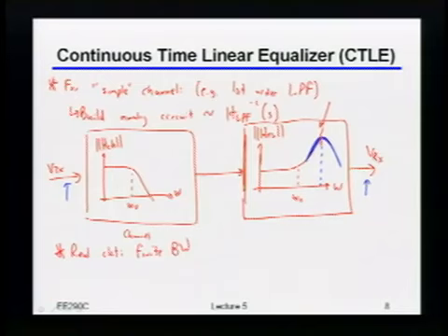Okay, so roughly speaking, where do you think, since you're building the circuit, you want to put this? 5 times the clock. Say that again? 5 times the clock. Oh, okay, so you said 5 times the clock. Remember, I'm working at about 20 gigabits per second. So that's, depending upon how you count it, somewhere between 50 and 100 gigahertz. Which, if you can do that in low power, great, we should talk.